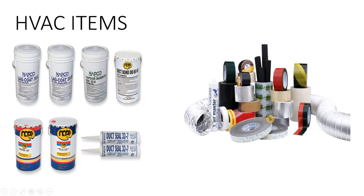Once you install the ducts, you will be installing the insulation. Thermal insulation you will be installing over that duct. How will you install it? Well, definitely we need some adhesives to stick that insulation over the duct, right? So we will be using these adhesives for that gluing purpose. Then we have sealant. For example, when you fabricate the duct, maybe there is some leakage from any joints. In those areas we will be using sealant. This is a type of sealant.